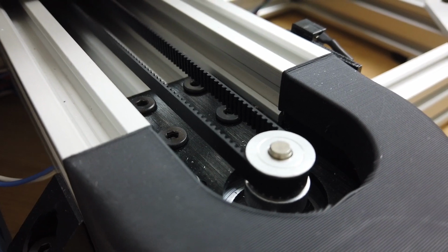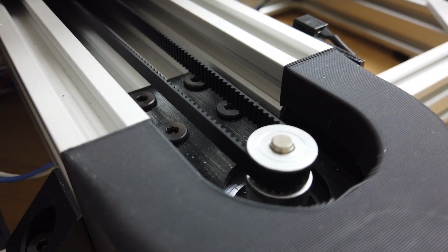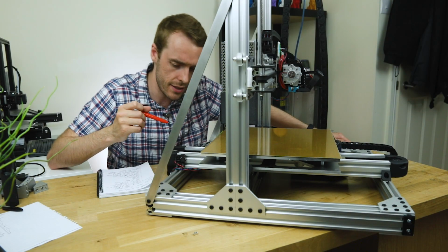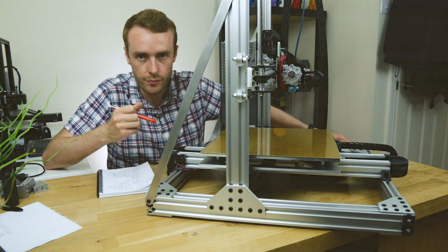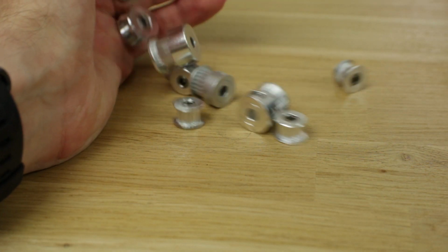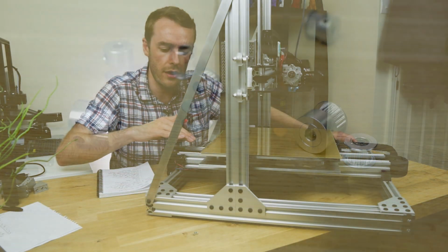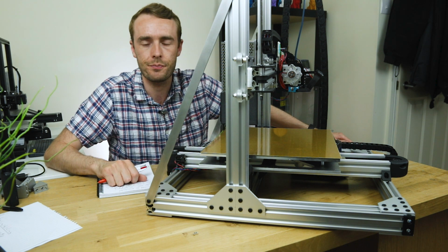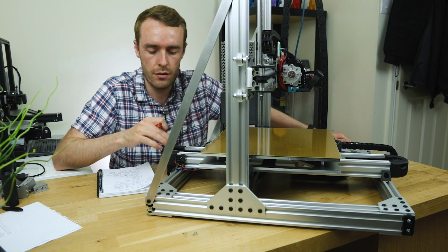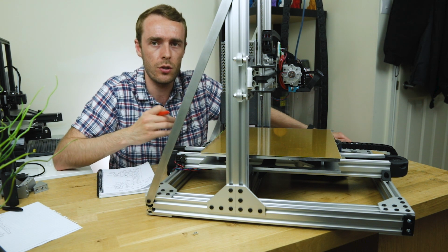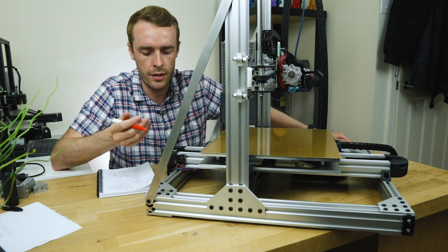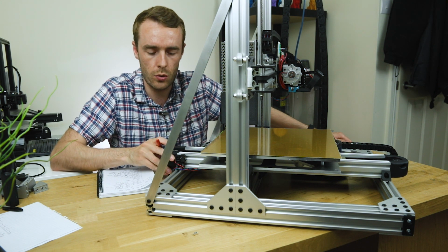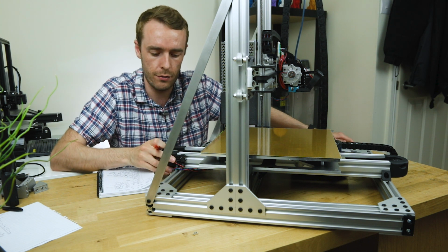Now, the next part of that is having a larger belt will probably also mean I have to have a larger pulley. So at the moment, the pulley is 16 teeth, I believe, or 20 teeth. And that is kind of a gearing ratio between the stepper motor and the belt movement. Well, basically the movement of the Y carriage. So the larger that wheel is, the less torque you get from your motor, but the more speed you get. Now, if we go larger belt and we have to go larger pulley, we're going to get less torque, less effective torque, if you like, out of the motor.